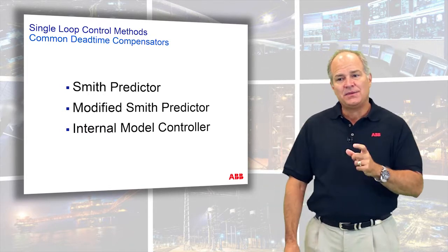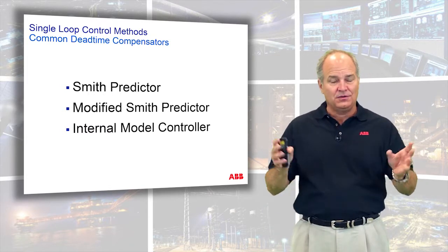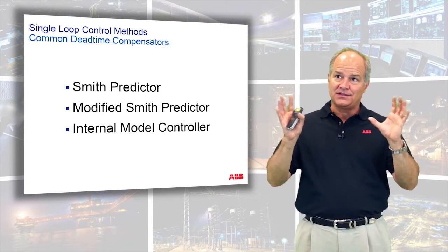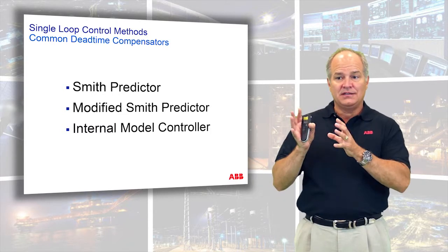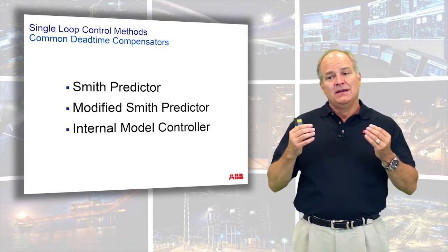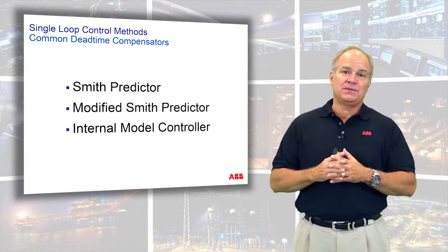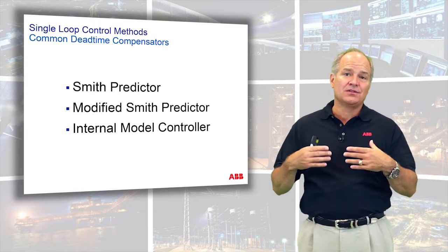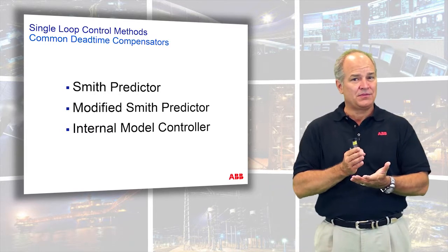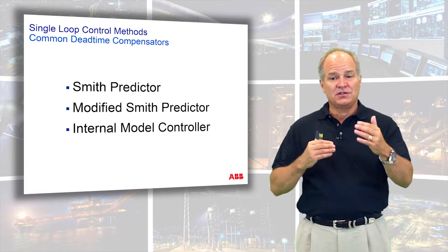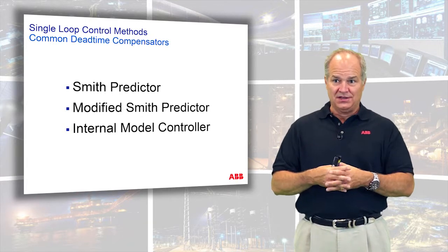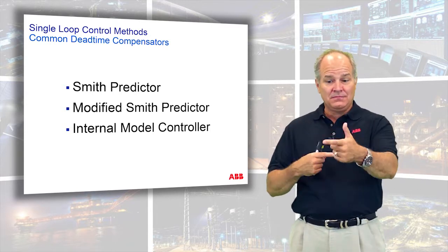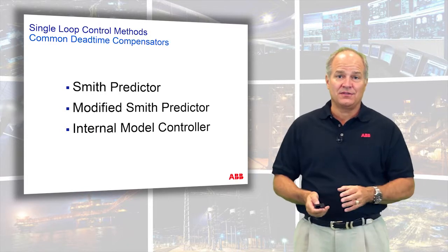standards, if you will. Smith predictor was the first, and you can Google Smith predictor, and that's a very well-known S-domain Laplace classic control algorithm that deals with that really well, and I'll cover that. There's a version of the Smith predictor called the modified Smith, which is a logical change, and I'll share that with you. And then there's the internal model control, or sometimes people refer to it as IMC, and it uses what's called lead lag technology, where the Smith and modified Smith use our old friend PID. The IMC uses what's called a lead lag technology, and we'll cover that.